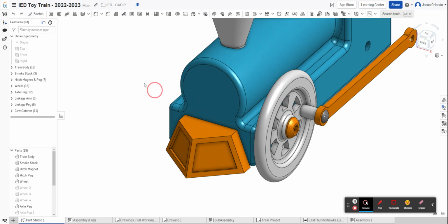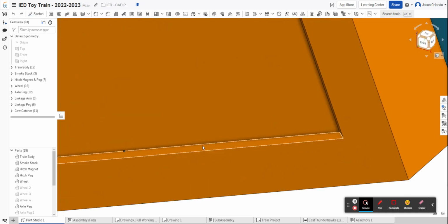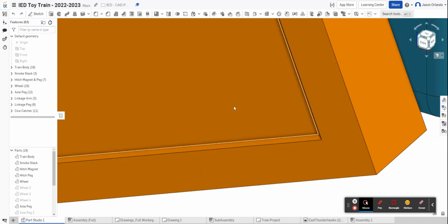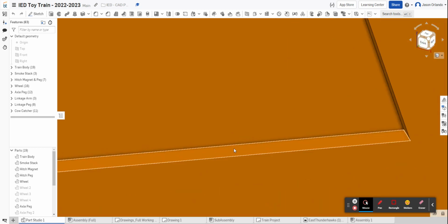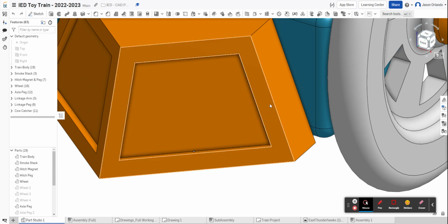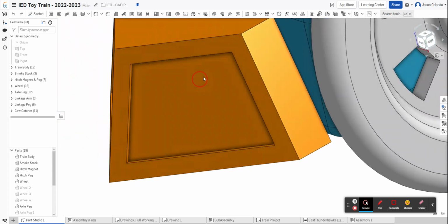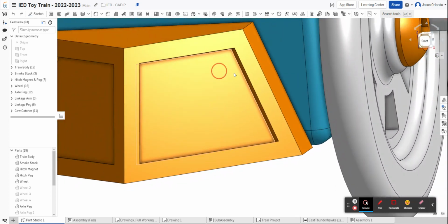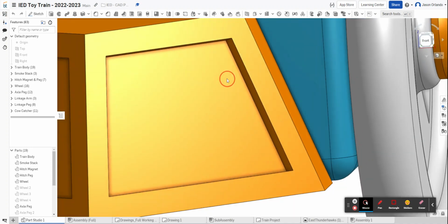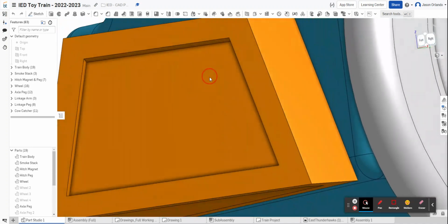Okay, so it's fairly simple though. The idea is we shouldn't see this little face on any of the 4 edges of the recess. If I can see that face on any of them, then I'm angled and not looking at it straight on. So if I can see that right one, the right's too far back, so I'm trying to get it so I can look straight on.